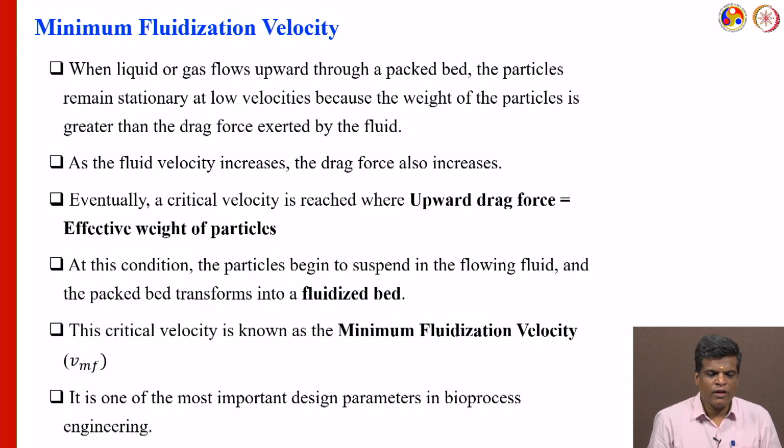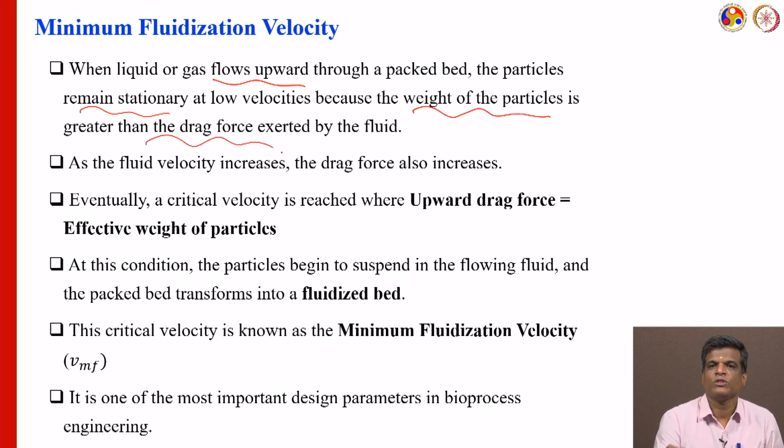So, today we will discuss minimum fluidization velocity. What is minimum fluidization velocity? A liquid or gas flows upward through a packed bed of particles, and the bed remains stationary at low velocity, because the weight of the particle is greater than the drag force exerted by the fluid.